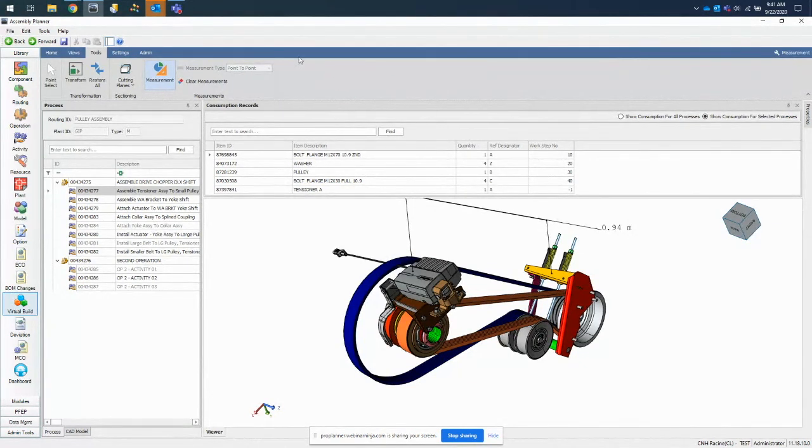As you notice, there's different measurement types. What you can do depends on how you open up the model. So when I brought up the original list of workspaces, I can specify a setting in there that will give me more flexibility when I open the model on which type of measurements I want to use. For instance, we can use point to point, which I just demonstrated, but we can also do part to part or even radiuses, on some parts that have that attribute, obviously. Okay.